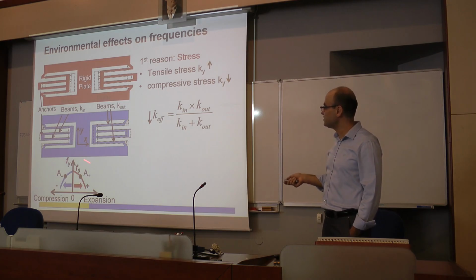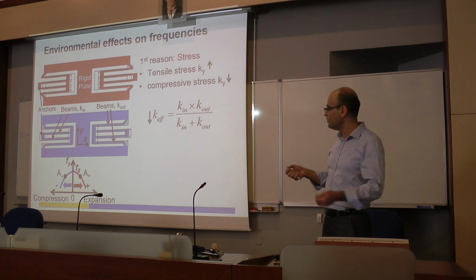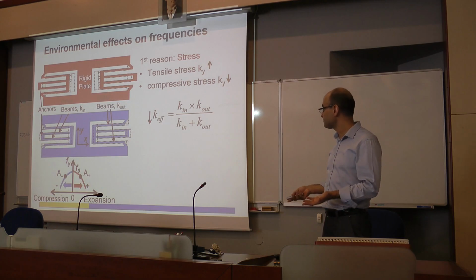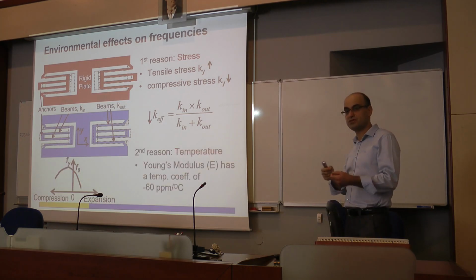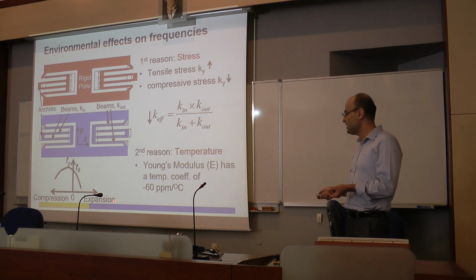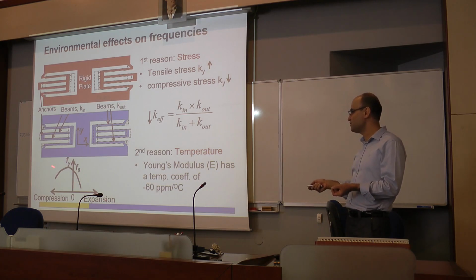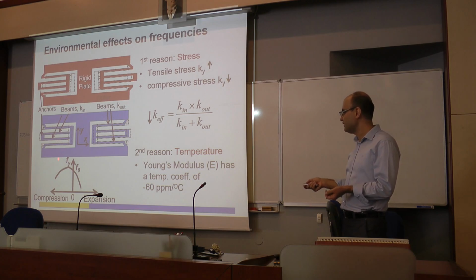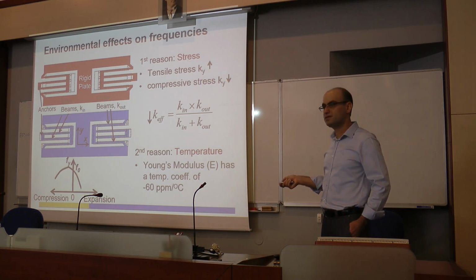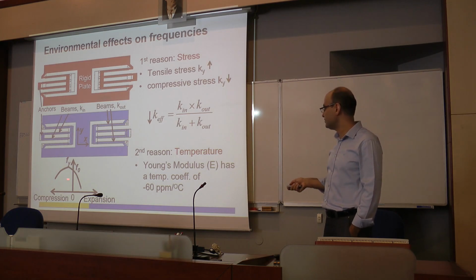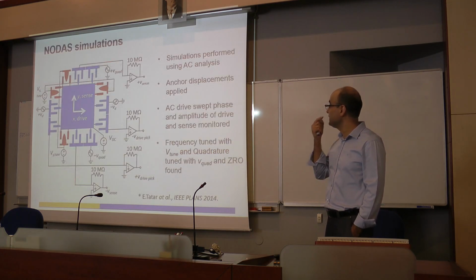So whenever you apply stress to this type of structure, whether you compress it or expand it, the resonance frequency always goes down. And we were doing it with temperature, so there's also temperature, and the temperature change is a line, and if you superimpose both of them, then you end up with something like this. So this curve is important, and in my measurements I will show you why this is important.